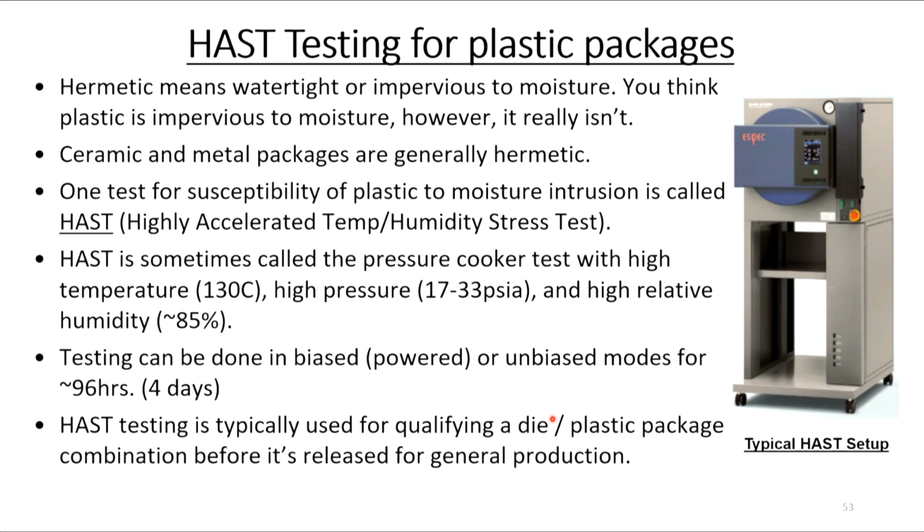So hermetic means watertight or impervious to moisture, and you think plastic is impervious to moisture. However, it really isn't. Ceramic and metal packages are generally hermetic, but one test for the susceptibility of plastic to moisture intrusion is called HAST, which stands for Highly Accelerated Temperature Humidity Stress Test. HAST is sometimes called the pressure cooker test, and it has high temperatures, high pressures, and high relative humidities.